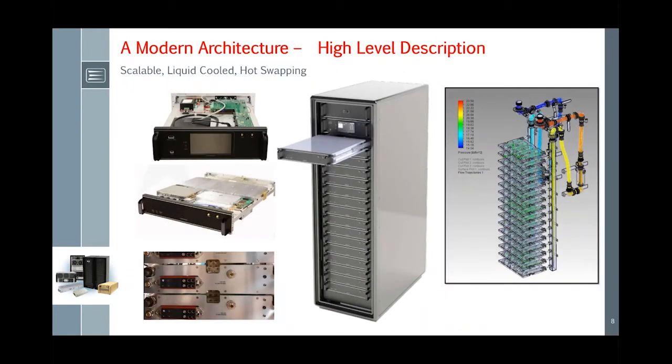And here's a visual of the system, a scalable liquid-cooled amplifier. The implementations here are usually broadband and CW or pulse. It's liquid-cooled for power density reasons. For example, an equivalent air-cooled system would be about 2.5 times larger. The amplifier consists of a controller in a 3U form factor, and in this case, 16 modular amplifier building blocks, 2U in size, and are fully integrated amplifiers in their own right. And we'll talk in some detail about that in the upcoming slides.